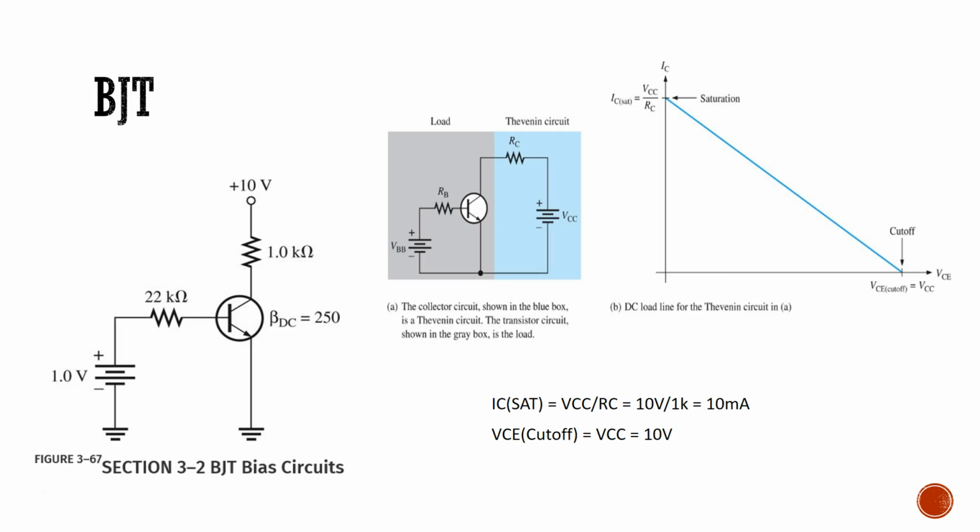The current at that point is 0 milliamps. Now, what that tells us is that, again, the point between the collector and the emitter measures 10 volts. That means this is consuming all the voltage and there's nothing left for the rest of the circuit.